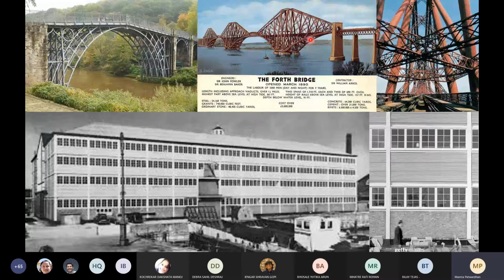These are all cantilevered. Can you see that? They're supported only at these 4 points. So these are cantilevers, these are tubular members that have been put together to create this kind of truss. These are riveted and bolted. Okay, write that down. It's the Forth Bridge and it's riveted and bolted. As against this, these were pins and bolts, while these are rivets and bolts. Okay.